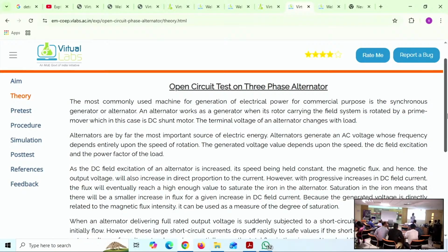That's the difference. Theoretically, as we are discussing, both are the same. Practically, that is the usual practice: we connect the ammeter first, then the voltmeter, because we are majorly considering the load voltages. So such points should be taken care of while conducting the laboratory experiments.